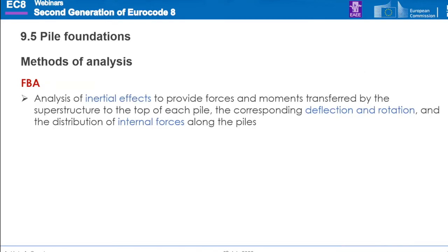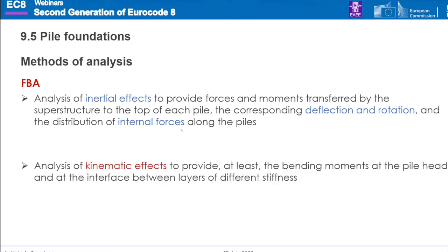Now, for the force-based approach, we are analyzing the inertial effects to look for the forces and moments which are transferred to the top of each pile, and looking at the corresponding deflection and rotation and distribution of internal forces along the piles. We are looking at the kinematic effects to provide at least the bending moments at the pile head and at the interface between layers of different stiffness.